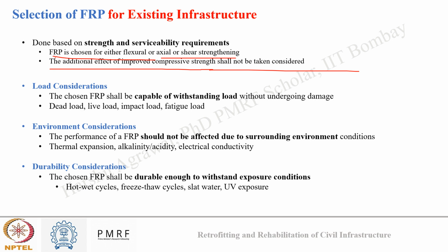Now these requirements of strength and serviceability can be judged by different factors. The first factor is the load consideration, that the chosen FRP shall be capable of withstanding load without undergoing damage. Okay, what are these loads? Dead load, live load, impact load, and fatigue load. So considering all these types of load, the FRP that I'm choosing should be able to withstand the load.